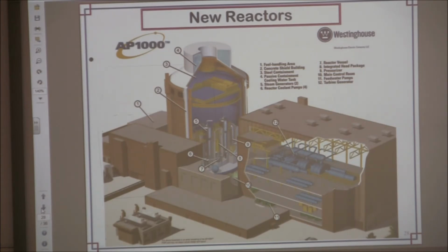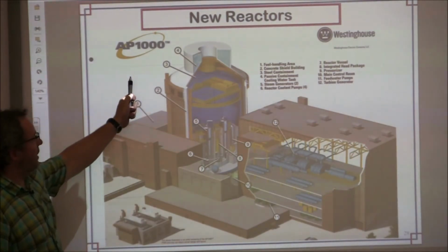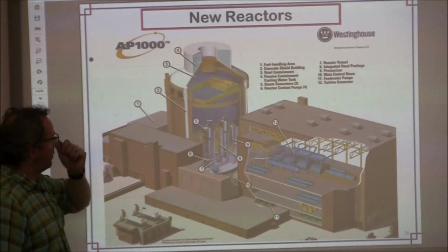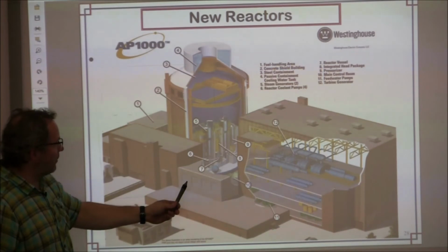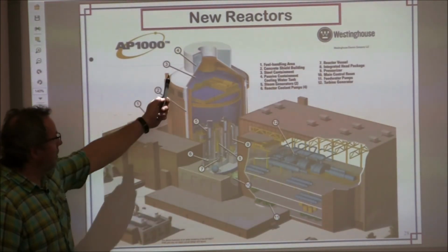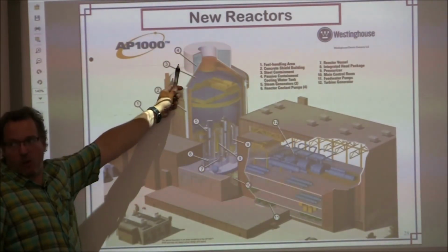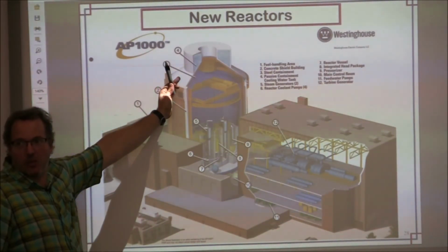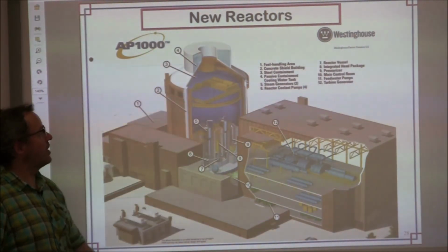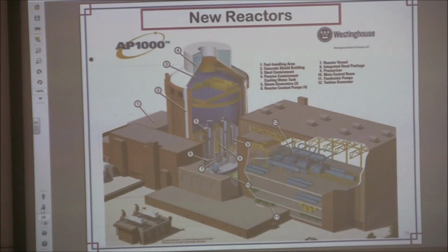So very similar, right? It's a pressurized water reactor. You have a slightly different containment structure, slightly smaller. You have a passive cooling water tank, which is located at the top of containment. So as it gets hot, this water almost rains down and helps to cool it. So instead of having ice, you just have a massive amount of water at the top.